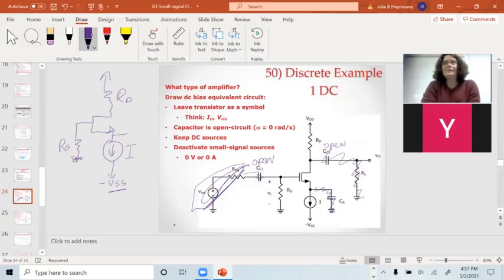An ideal current source drops whatever voltage it needs to keep the current constant. You have no information about what VS is based upon that current source. You don't know how many people I've seen do that on an exam. Just call it the power supply at the source. It's the negative power supply for the chip.